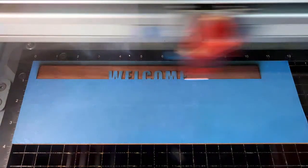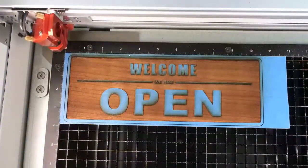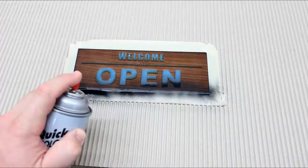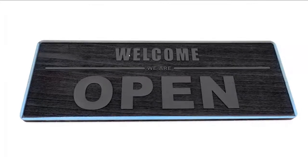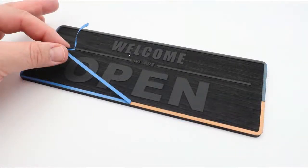So the laser is going to etch away all the black, leaving the letters on the surface. And so this is the case where the wood is not producing enough contrast, but I still want the letters to look like the wood. But I also want the background grain still to show, so it still kind of looks like wood. So in this case, I've masked off the whole thing, engraved everything except for the letters. And then after I've spray painted it, I then peel the mask off the surface of the wood.